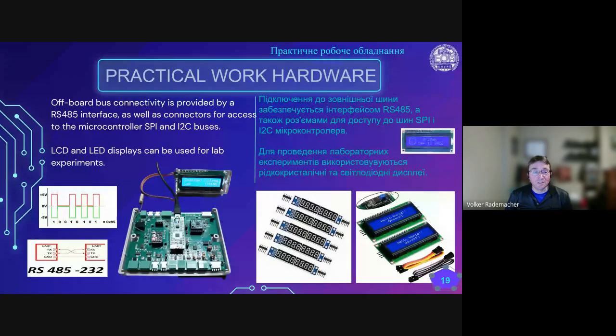If you just need some measurement data from a sensor that's 500 meters away, then RS-485 is just simpler to use. And of course the RS-485 interface would be a typical method for connecting to an embedded PC or a single board computer if you have a system that consists of several of these devices.